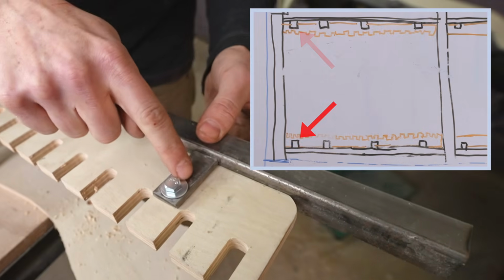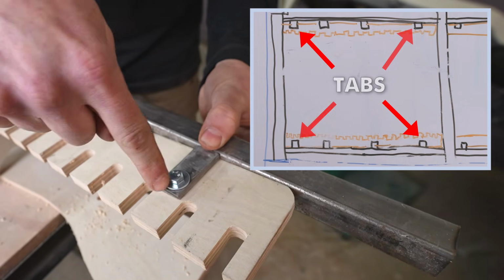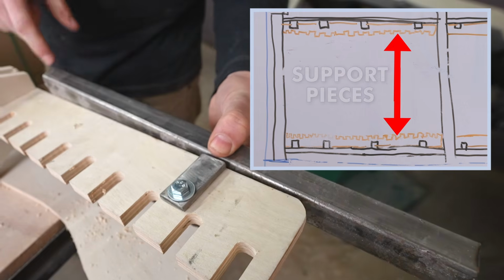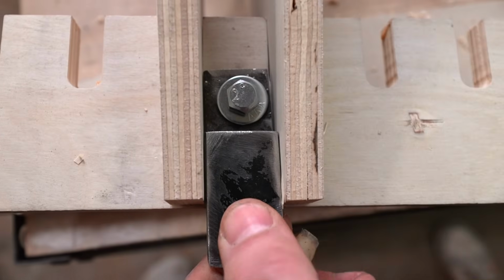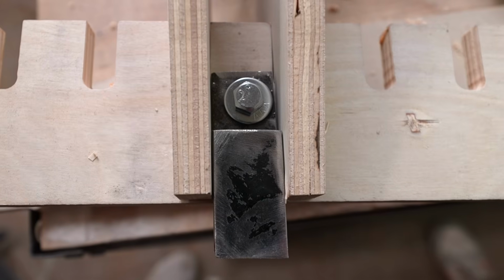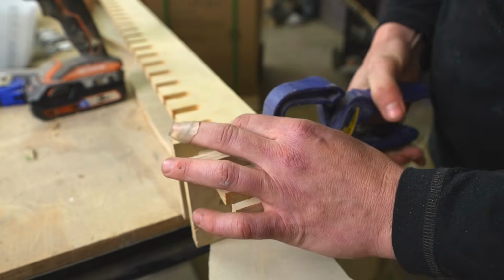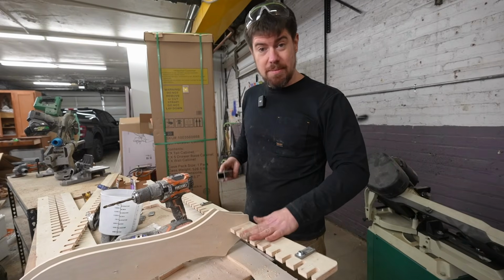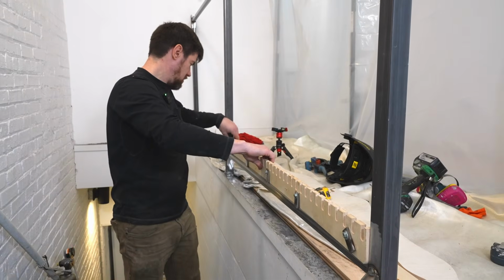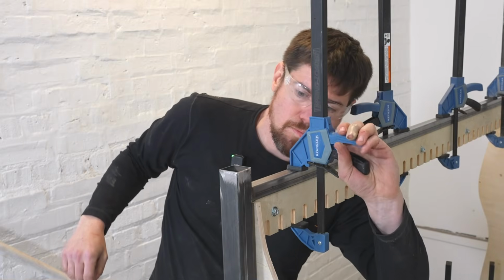We're gonna have these little tabs here that are gonna be welded to the support rails and then bolted to the support pieces coming here. One major consideration here though is that as these tabs are coming up, they gotta fit exactly between here so they don't block any of these. So what we're gonna do is first precisely drill all the holes for these bolts in the cross pieces. Then we'll take the cross pieces up to the railing and use these support pieces with the tabs bolted to them to hold the tabs in place as we weld them to the rail.